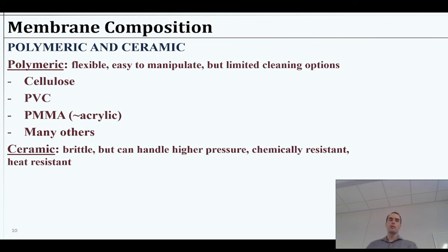But there's actually some advantage if you can use it as hot water, because if you remember, we'll talk a little more about this, but viscosity is going to be related to how easy it is to push water through some porous material, right? We've seen viscosity important in several things by now. And so with high temperatures, the viscosity is lower.